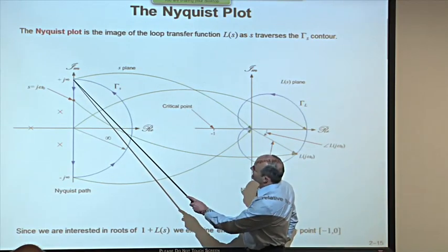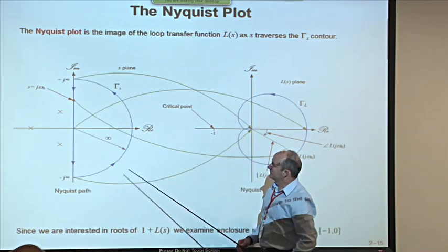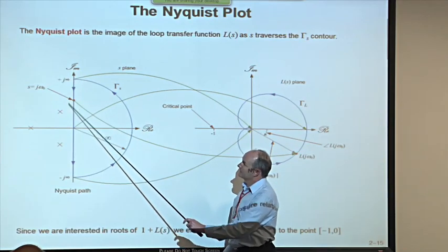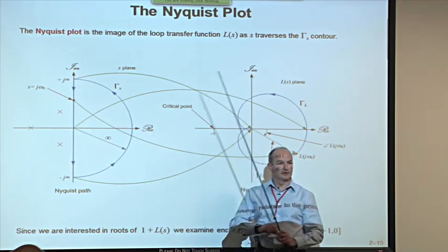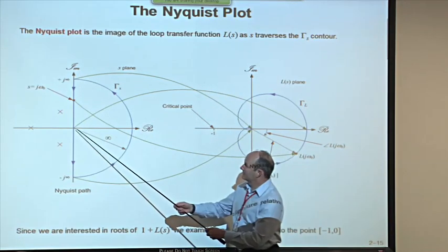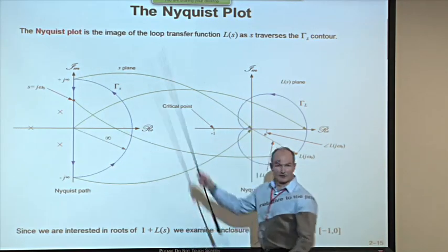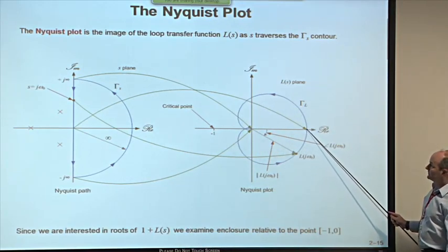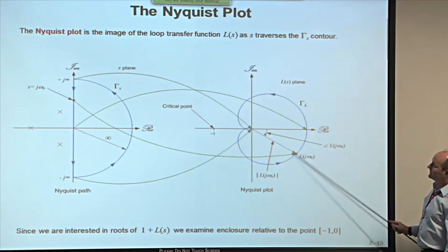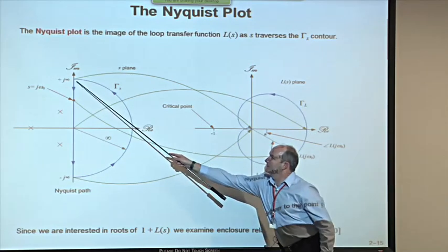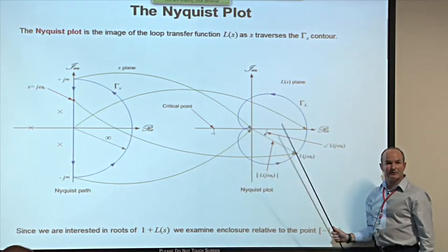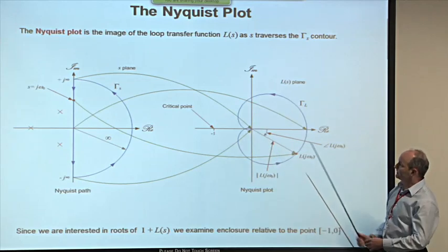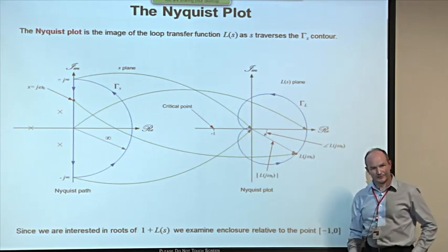And what you find when you use this technique is that points infinitely far up the imaginary axis correspond to infinite frequency, and the point at the origin corresponds to zero frequency. So the positive imaginary axis corresponds to a line of varying frequency from 0 at the origin to infinity up there. And you can expect that some transfer function is going to have a magnitude which varies from, say, some finite value towards 0. So this point here typically gets mapped towards the origin of the curve that's over here in the mapped contour. Okay? Anyway, this is typically how you would construct a Nyquist curve.